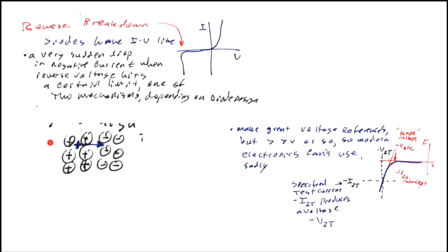This is an N-type region, and the minority carriers are holes. And if we had a hole in the depletion region for some reason, and actually holes don't have to wander into the depletion region. They're made by magic everywhere in the semiconductor, just by thermal energy. And so holes will get created in the depletion region once in a while. And once you have a hole there, it feels a tremendously strong negative voltage on the other side of the depletion region, and it'll be accelerated across.